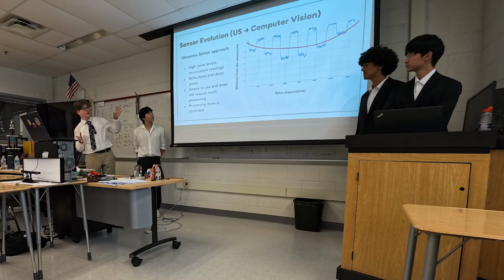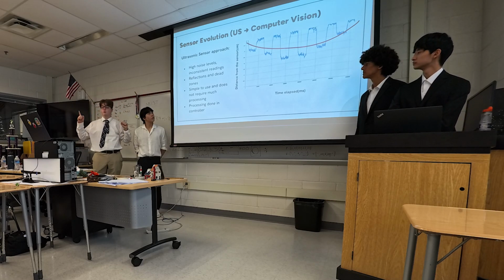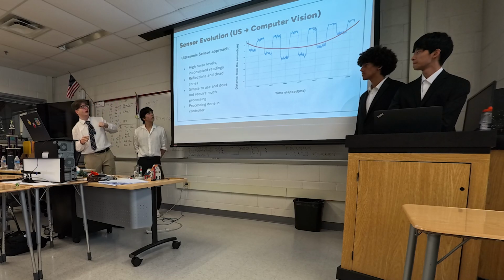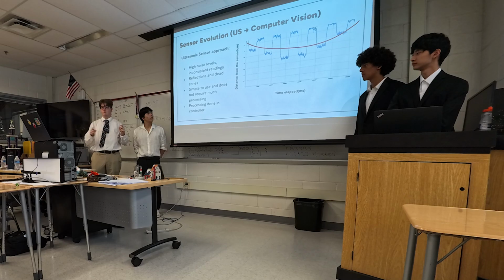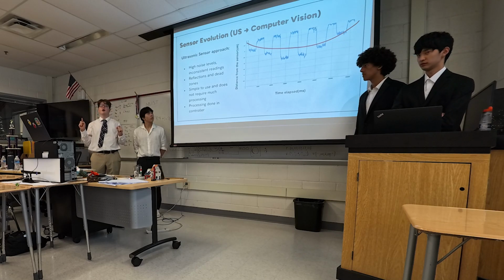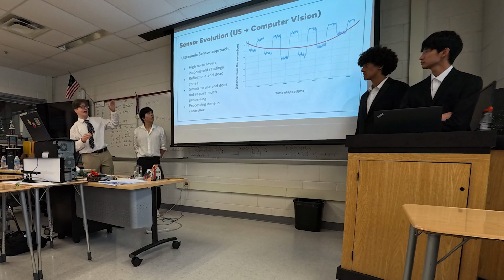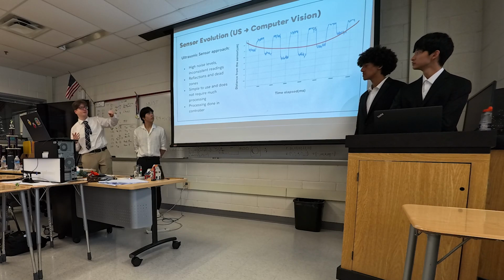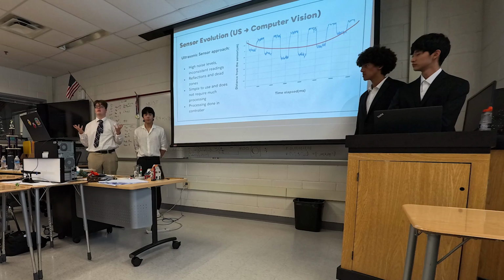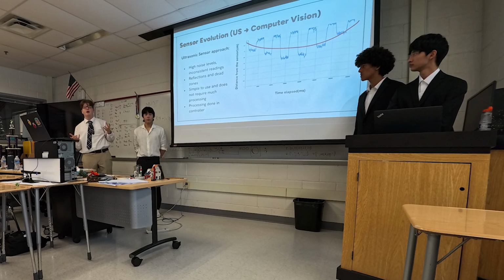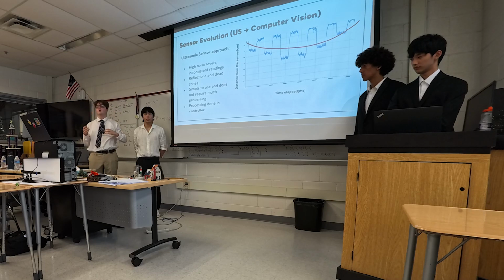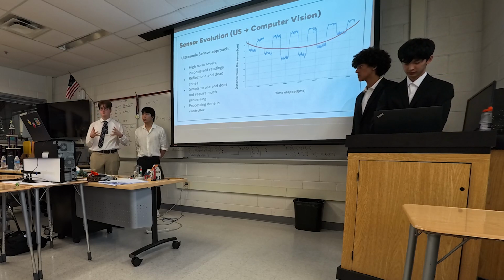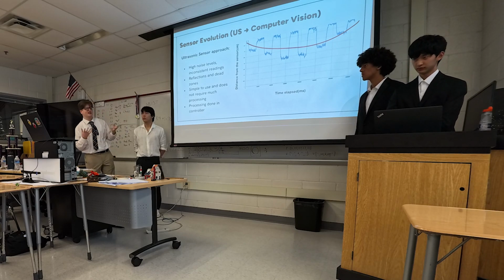And here, I want to explain some things. This graph is showing the ball moving back and forth on the beam, and the blue line is what the ultrasonic sensor is measuring. This is very zoomed in, but we expect the movement back and forth to look like a sine wave. But instead, on the blue, it jumps around. It has a shape reminiscent of a sine wave, but do you see how it jumps up and then jumps down? This is very problematic because it shows that it does kind of know where the ball is, but not really, as it tends to jump around and spike a lot. For things that require a lot of accuracy, specifically when we want to match it to the simulation, this doesn't work out well.